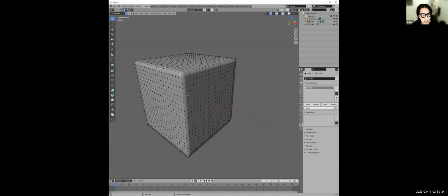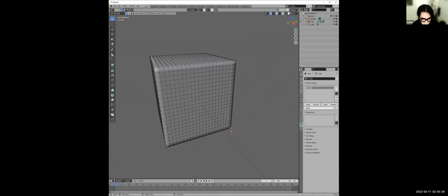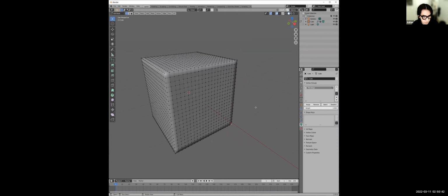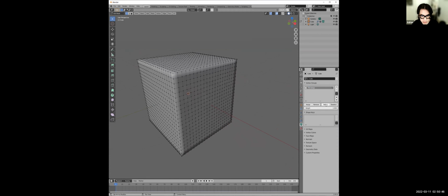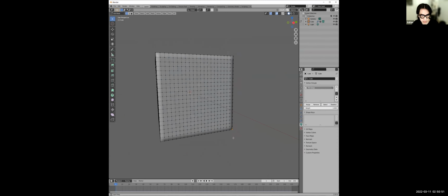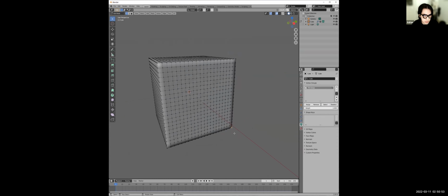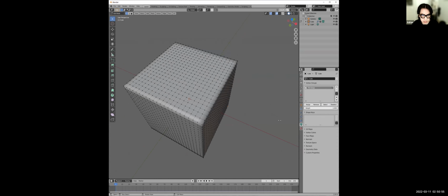What's really important is to click assign, so that now this point is assigned to this group. Otherwise, it won't work. So make sure you press assign. We'll double click this group and we'll just rename it something for reference, like pin group. And if we click here in the space to deselect it, and then we click select under pin group, we can see that is now selected. So yeah, just make sure that point is selected.